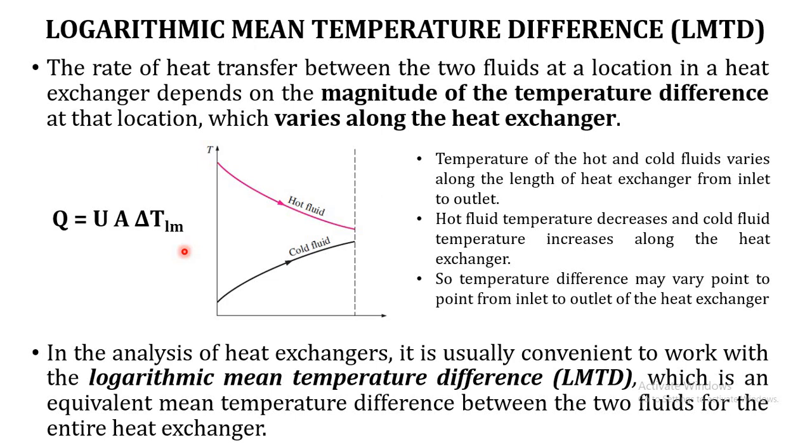So it gives a constant heat transfer rate throughout the heat exchanger. Actually at the inlet the heat transfer will be more, and at the exit the heat transfer between the hot fluid and cold fluid will be less in the real case.